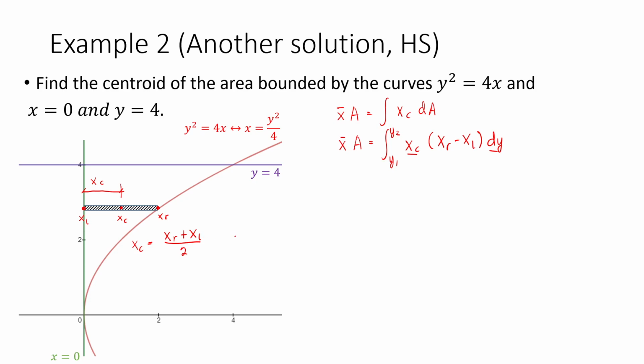So again, why we need to get the midpoint formula in your x sub c at this point, because again we are integrating with respect to y, and we need to represent our x sub c in y variables for us to be able to integrate. Same goes for the vertical strip earlier. Once we reached the bar y portion, our y sub c should be represented in x variables because we were integrating with respect to x earlier. Right? Now we're integrating with respect to y, so x sub c must be represented in y terms as well.